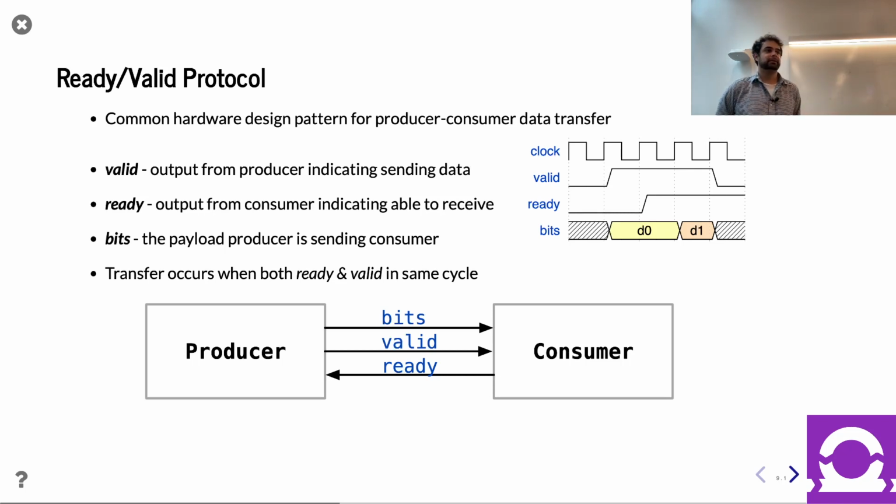Yeah, there's IP out there in Chisel for AXI, but I don't believe AXI is in the standard library. But there is Chisel IP on the web for AXI, and this is the kind of thing where you're asking great questions. What if you became convinced you had a better handshaking methodology that was perhaps either more gate efficient or more timing path efficient, and you wanted to make that? You can make that. That's what's cool about Chisel, right? You can just write it and then share it, and boom. If you want to change Verilog with Verilog tools, it's not really something that's easy to do, but you can make your own Scala library, put it in there.